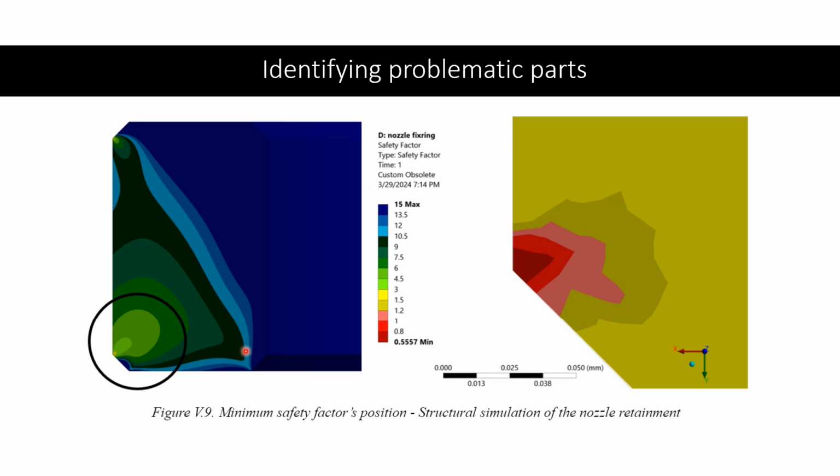And when it comes to this, of course we cannot say that this part will fail, because when we zoom in we can see that this numerical error is very small. And of course the question arises why these solvers make such errors. It is not a big problem, because everyone can see that it is under 0.05 millimeters. This is the first thing, and the second thing is that it is due to the poor definition of boundary conditions.